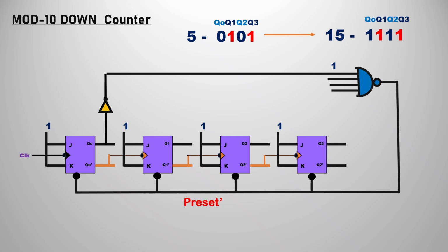So we should connect the NAND gate with the help of a NOT gate. So that becomes our first output. For that we need the NAND gate output as 1, but we need to have the NAND gate output as 0. If the NAND gate output is 0, we have bubbles, so both bubbles will be cancelled. Means the NAND gate output is 0, and again you are going to invert it with the bubble attached to the flip flop, so that will invert it, making the whole output preset bar 1.